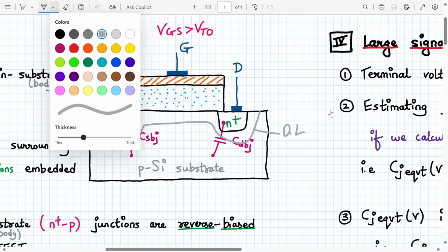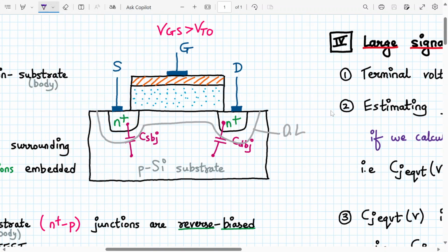Normally drain voltage we apply positive, right? Now we apply this positive with respect to the source terminal. This is negative. Yes or no? And the body normally is connected same as your source terminal. So this is normally grounded. Okay, sometimes if VSB is not equal to 0, that means our source to substrate bias is not equal to 0, and for this case, your threshold voltage becomes VT instead of VTO.